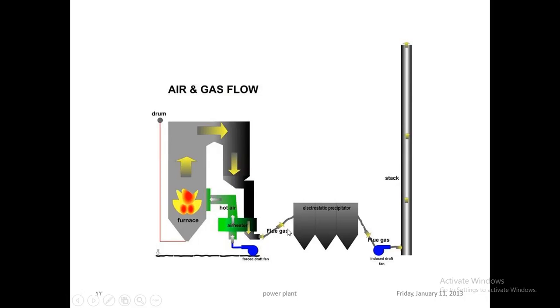Furthermore, these gases contain tiny particles which have to be collected at this section, called the electrostatic precipitator. In this section we collect the particles that can damage the induced draft fan, because that fan extracts the gases from this section and provides them to the chimney stack. The chimney is the way to release the carbon emission and toxic gases to the environment after treatment.